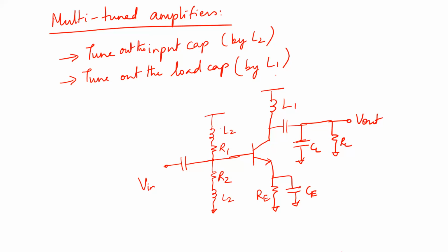You have two RLC networks here, both in cascade. So basically, you will have some A divided by S squared plus 2 alpha 1 S plus omega naught squared, into another B over S squared plus, let's say, 2 alpha 2 S plus omega naught squared. Now you have a fourth order network.